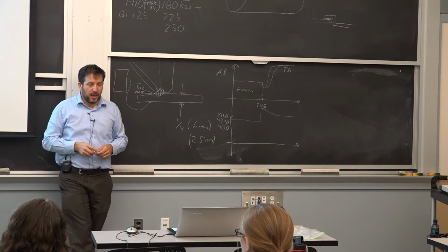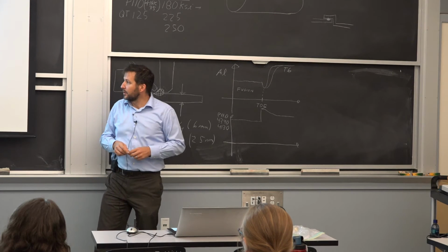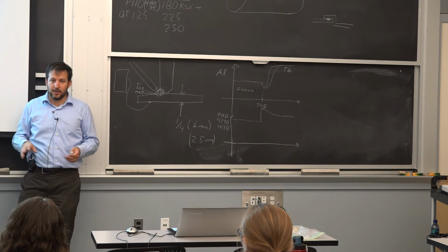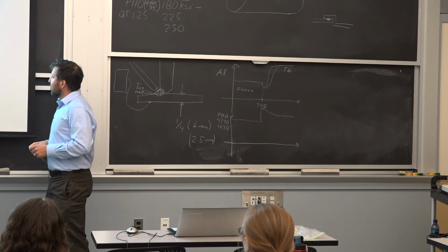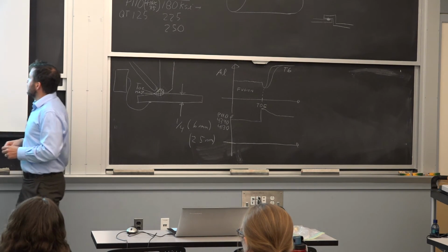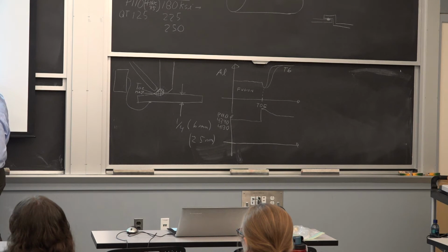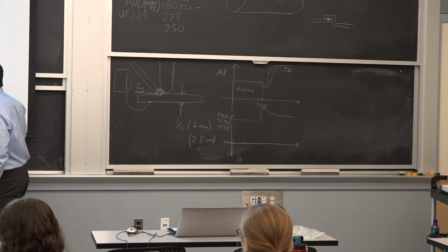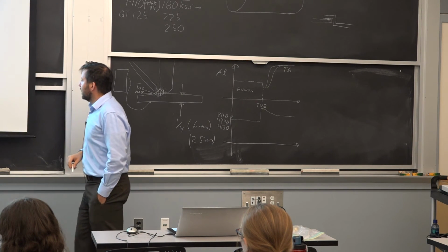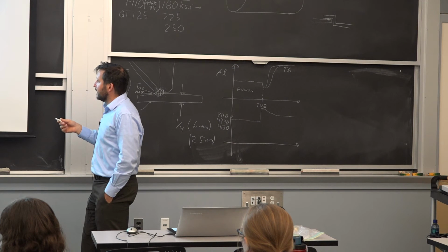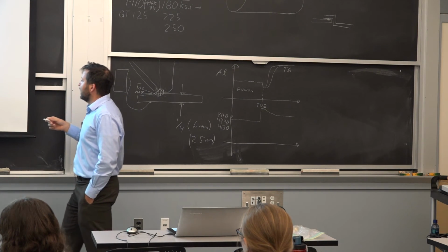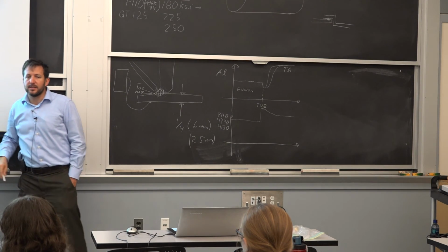Now, if you have other welding processes that we'll talk about later, you can't do that. Everything needs to be clean in the first place. So what else is there to say here? So we essentially have that consumable here that forms into the slag. We have the metal that forms the fusion zone. We have control of speed, and all the electrical control defines how much heat you're providing.